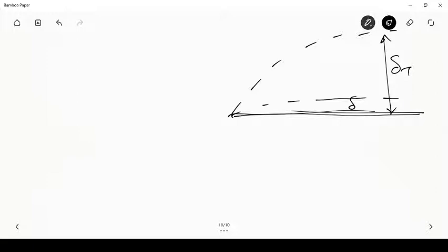Okay, there's a plate, and let us say this is the thick thermal boundary layer and this is the thin momentum boundary layer. So this is delta and this is delta T. So delta T is much thicker than delta. So what happens? The velocity reaches u infinity right here and remains u infinity throughout the thermal boundary layer.